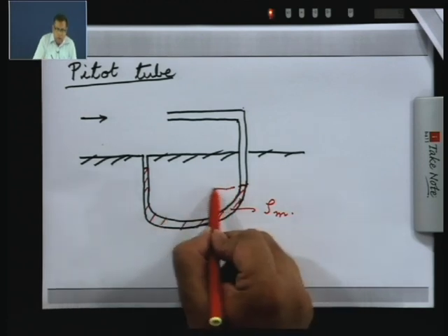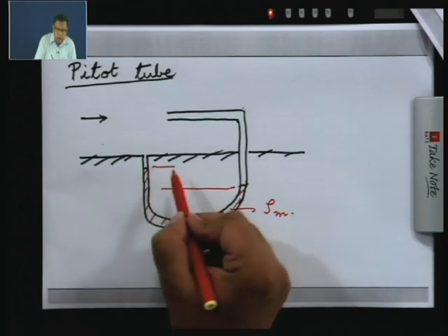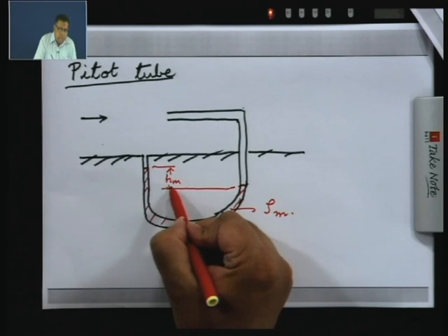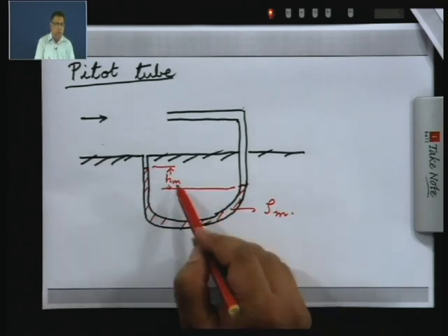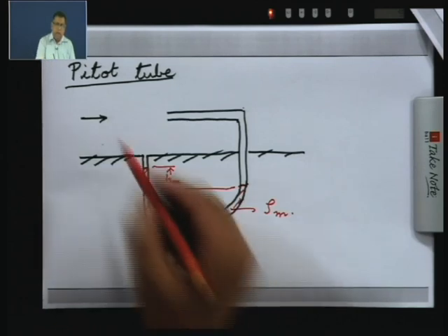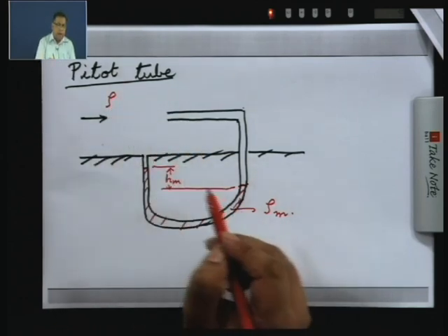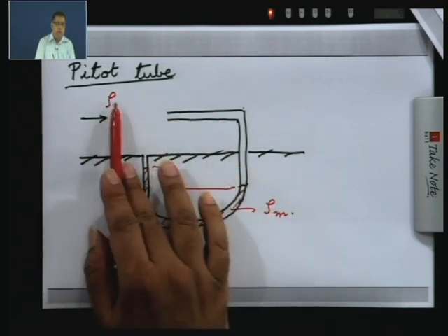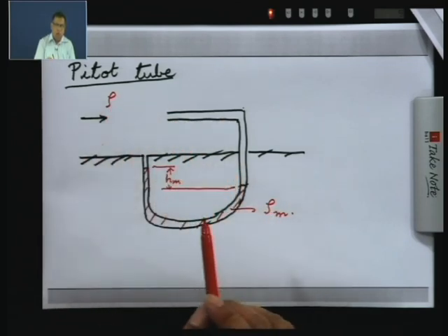Now, in the lab what you can do is measure this manometer deflection, which we will call H m. So, the subscript m refers to the manometer, and the density of the liquid or gas, whatever it is, which is at low speeds, which is flowing over the wall, we will denote by rho.